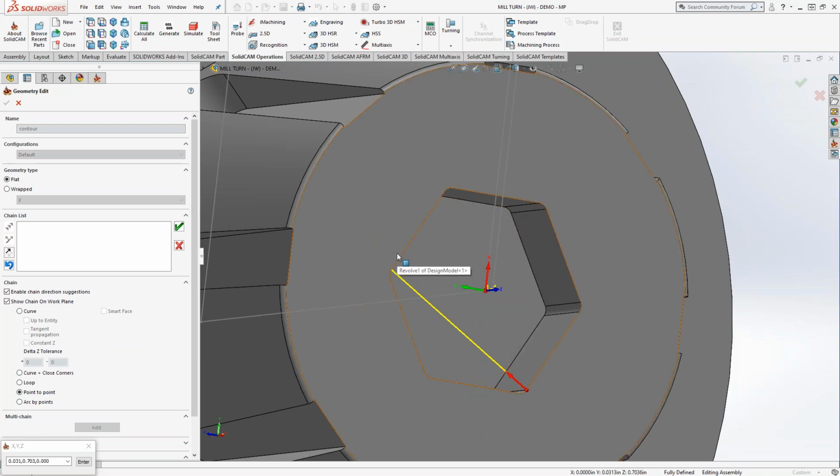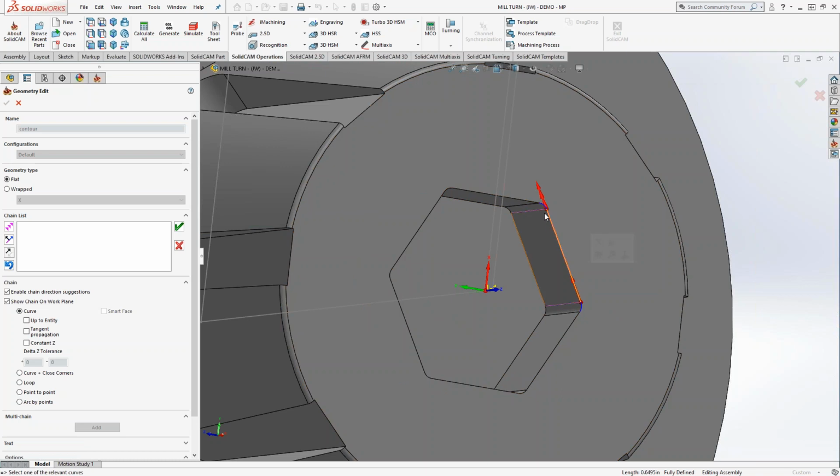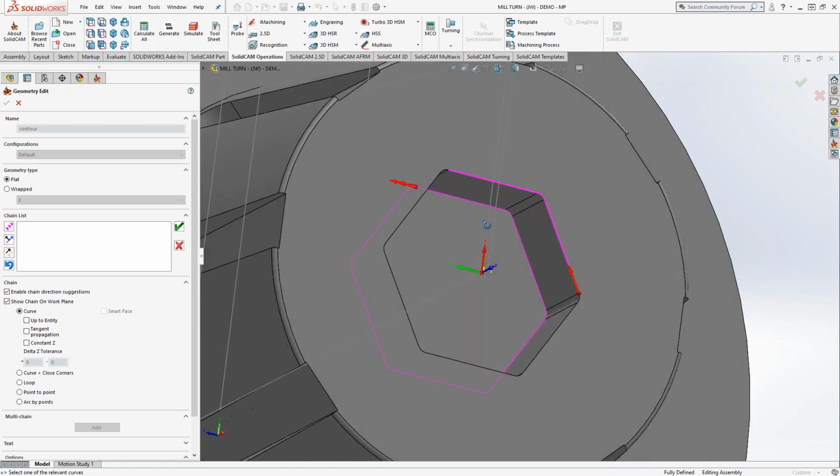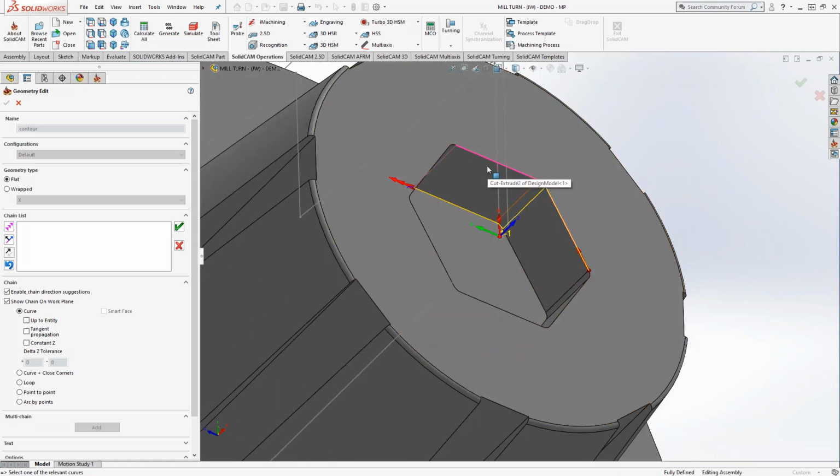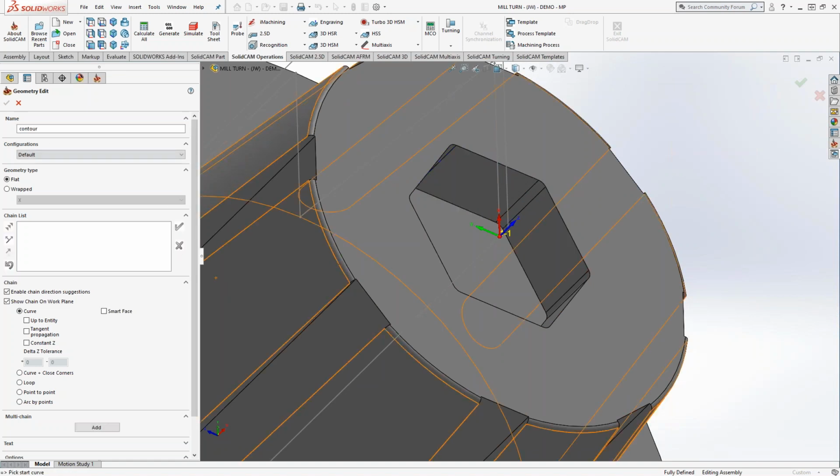So if you already have the slot there and you're looking to jump the gap, like Kevin said, you want to open some edges and take advantage of that open area, you can do that. If the slot is not currently there and in the order of operations you're just doing the pocket right now, you can use point-to-point to close those edges. Or always remember as well that it doesn't matter which direction you go with your chain. You can go like that, you can go down, across, like that, and all you're looking for is that projection to the tool plane. So if that slot makes part of the wall, then you can go up and down in your chains as well, and then just get that to be part of your pocket geometry as well. That makes sense, Frank?